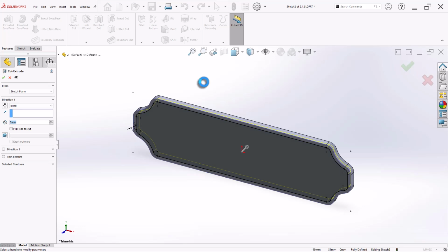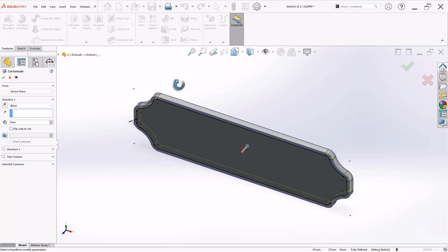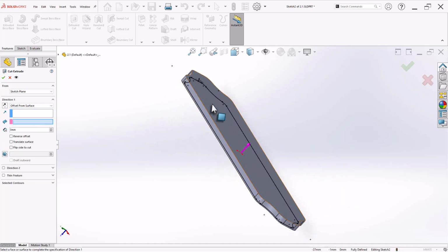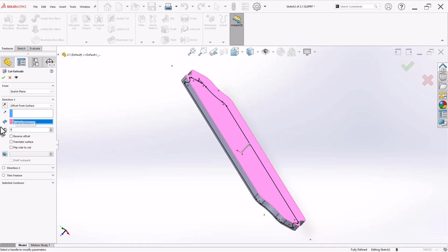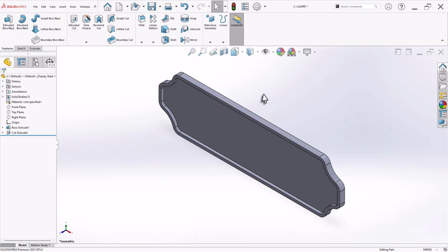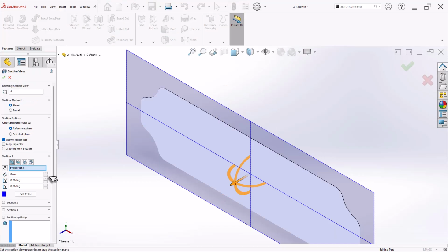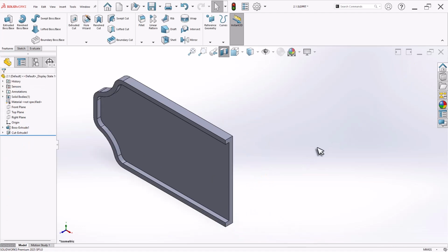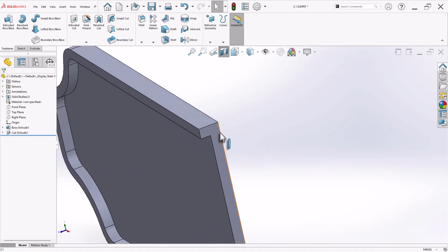If you look at the detail view, it is given that the cut is extended with the given relation from the backside, that is 1.5. So here I will choose offset from surface, this one, and I will add 1.5. So how do I know that? So let's cut this model. So here it is given, from this thickness is 1.5.